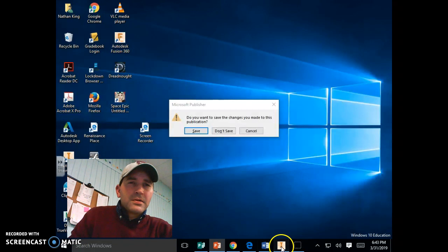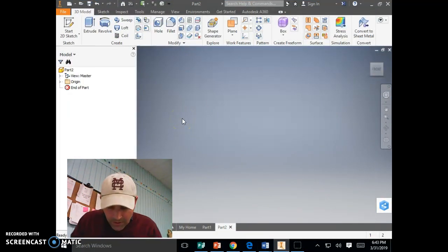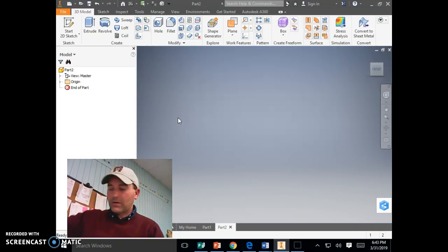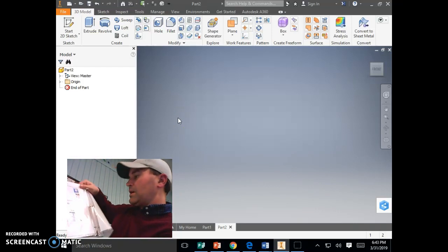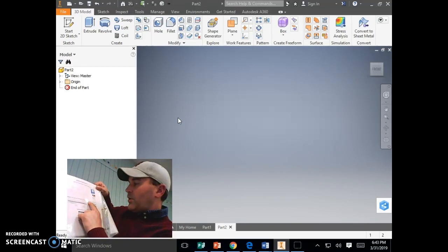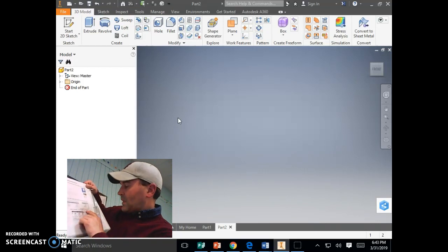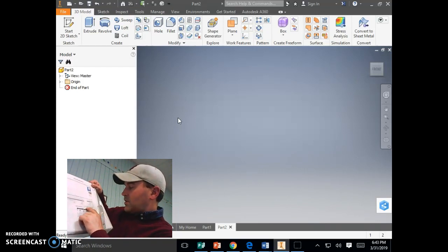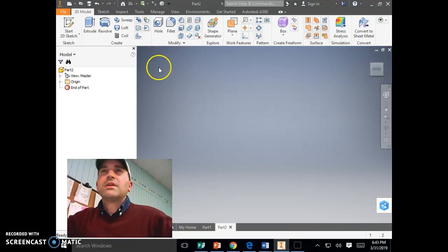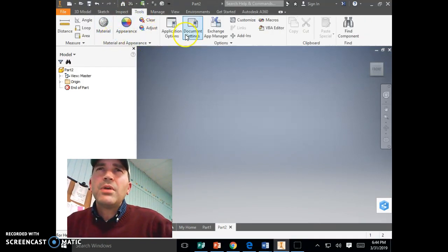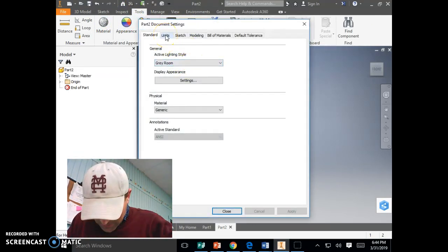Okay, so alright, so let's go to step 1. It says click new. Then I'm going to hold it up like this so you can see it. So create a new Inventor part by double clicking, and then click standard.ipt. Alright, the next thing says change the unit of measure. Click on the Tools tab and click on Document Settings. So I'll go up here to the ribbon at the top where my mouse is. I click Tools tab and I click on Document Settings, which is right here.